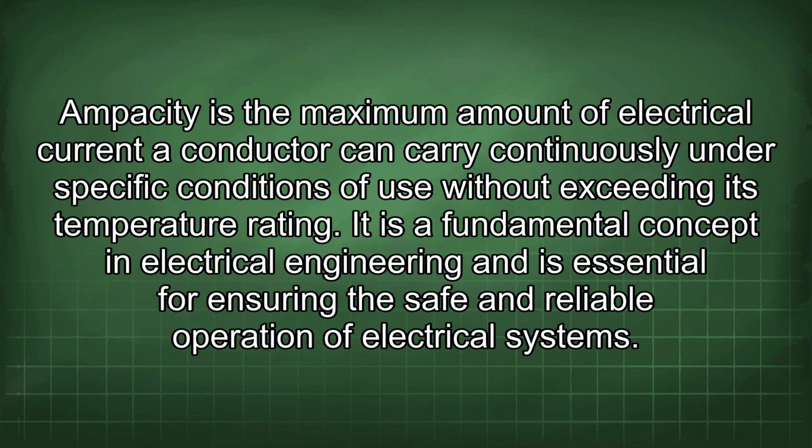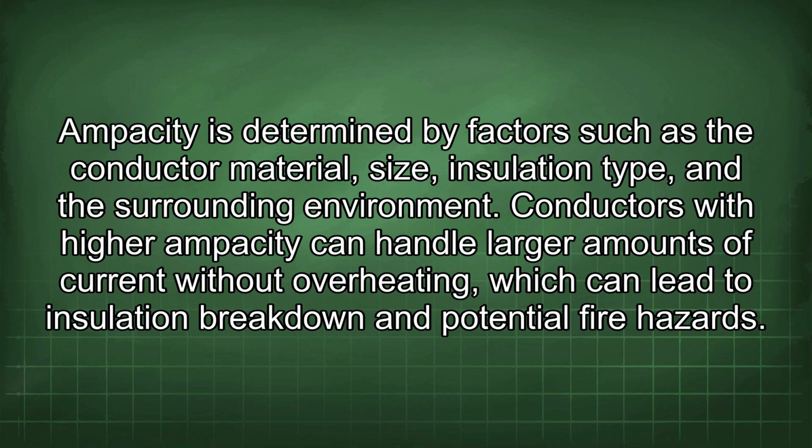Ampacity is the maximum amount of electrical current a conductor can carry continuously under specific conditions of use without exceeding its temperature rating. It is a fundamental concept in electrical engineering and is essential for ensuring the safe and reliable operation of electrical systems. Ampacity is determined by factors such as the conductor material, size, insulation type, and the surrounding environment.